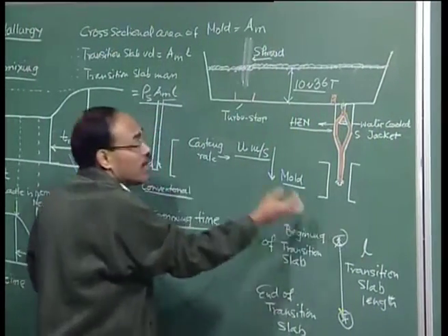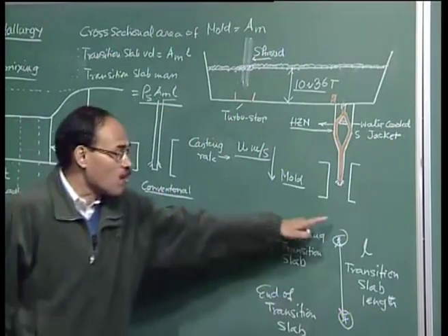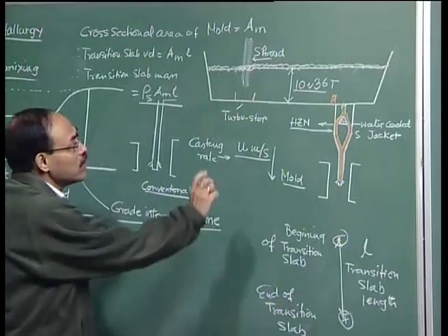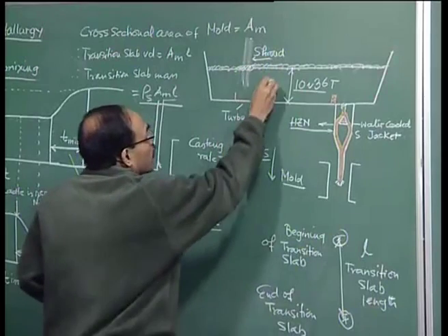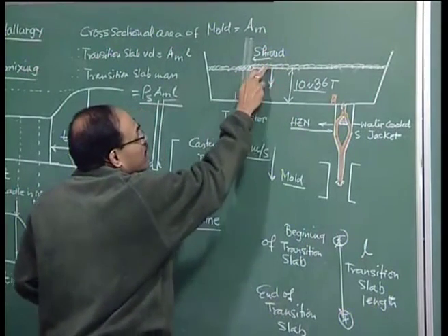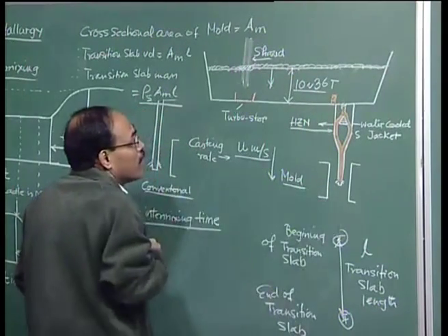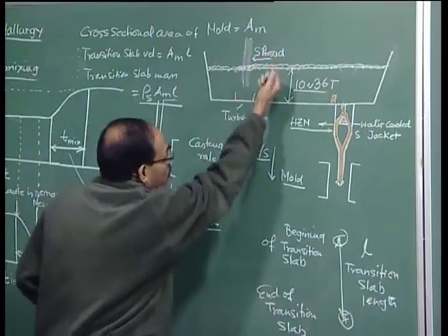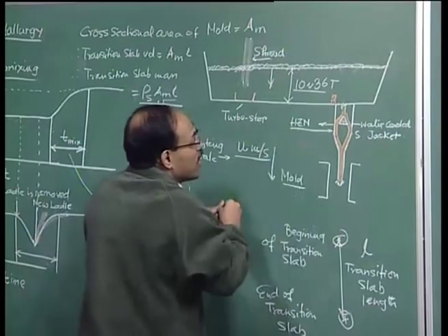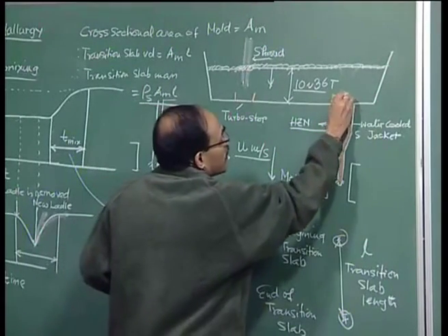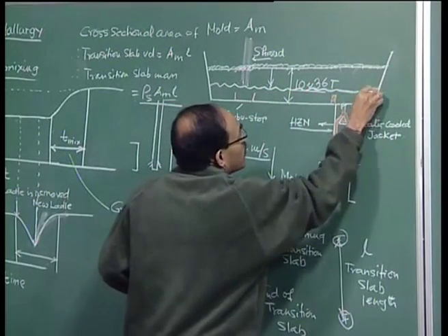Now the casting goes on, and the objective is to salvage the entire amount of steel out in the form of solidified product. But as I have mentioned already, the depth of the liquid falls down, as the surface descends. Why does the surface descend? Because nothing is coming in, the material is only being drawn from the tundish. So, the bath depth really decreases, and as the material drops down, immediately above the nozzle there is a formation. So, imagine that the material now has this level. Okay. So, the slag is here.